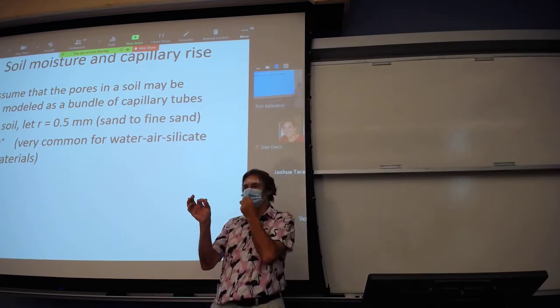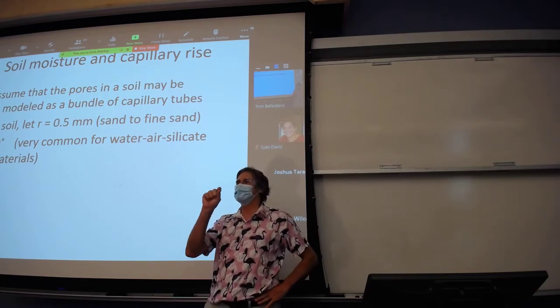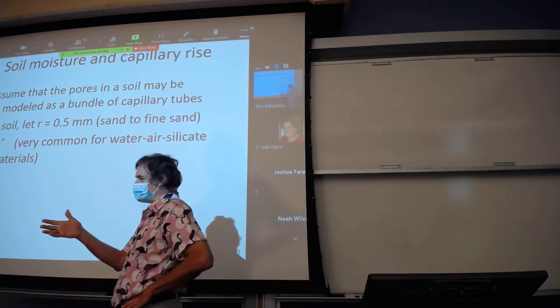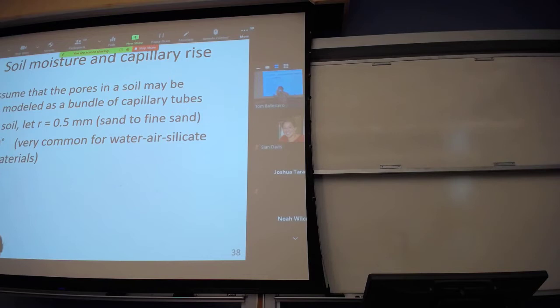Typically, the diameter or the size of the pores is on the order of D10 of the soil. So I know not all of you have soils, but the environmentals and both the civils will do particle size distributions in different courses. In a particle size distribution, you're measuring the smallest particles up to the largest. And you do that by identifying a size at which a certain percentage is smaller than.